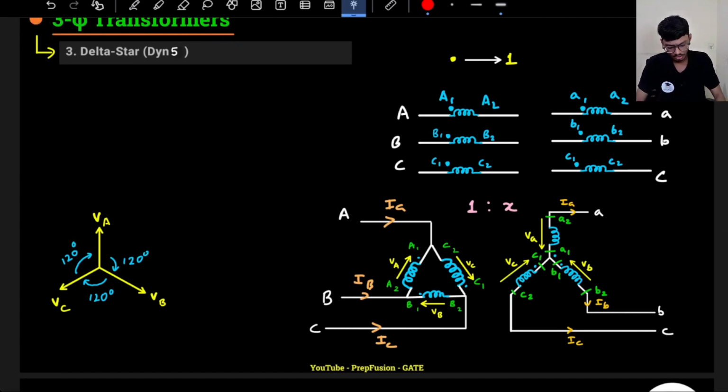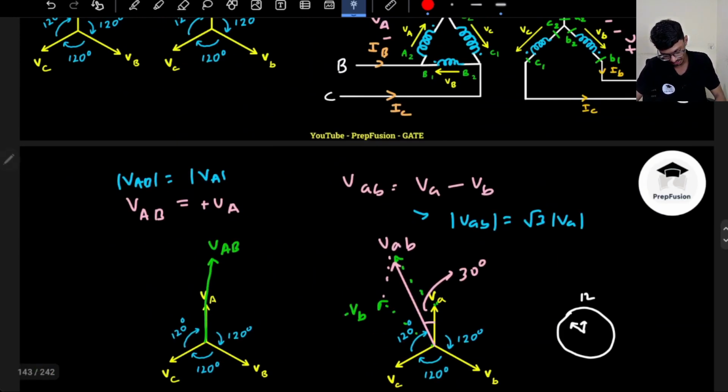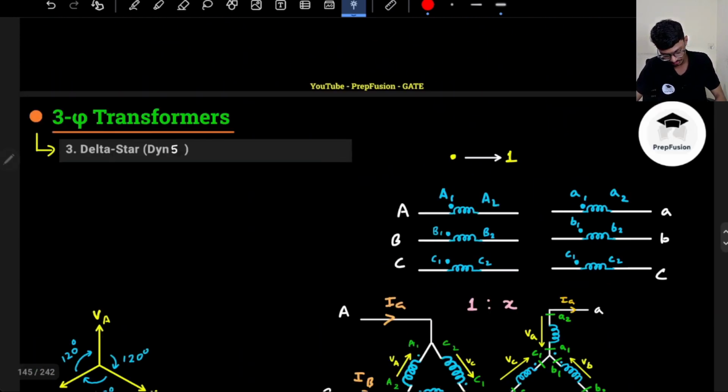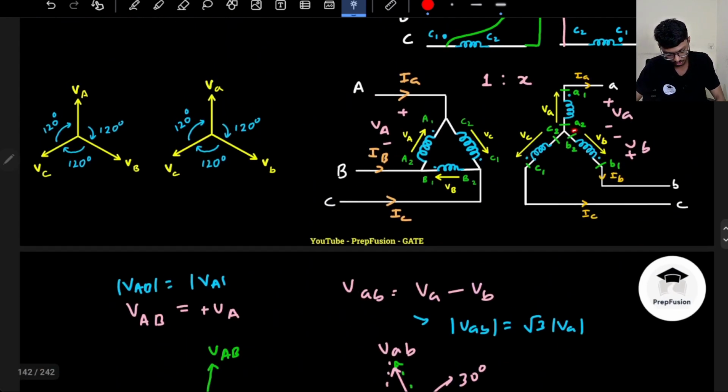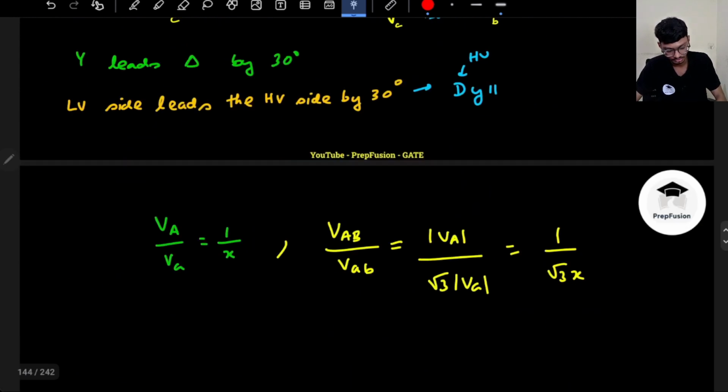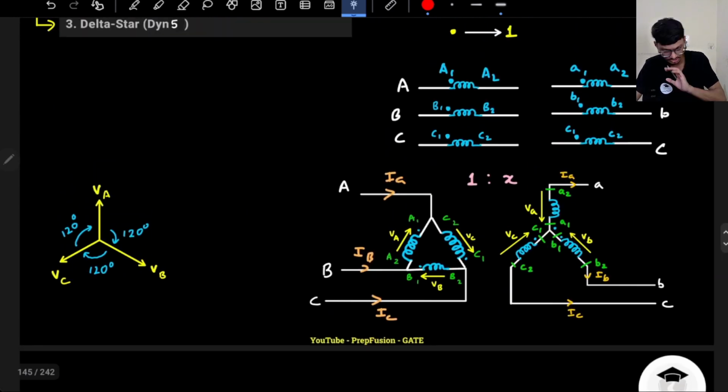So now what we are connecting is A1 C2, same as here as well. We are connecting A1 C2, so the high voltage winding is the same. The low voltage winding we are swapping. We are swapping A2 and A1. So A1 is now the common point, so A1 C1 B1 all are common. We are just swapping, so basically the phase will be totally shifted again. That is what will happen here.